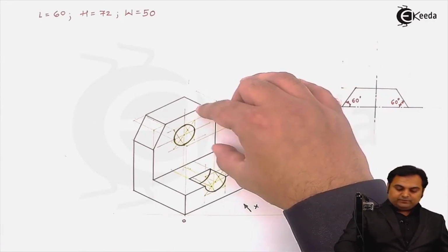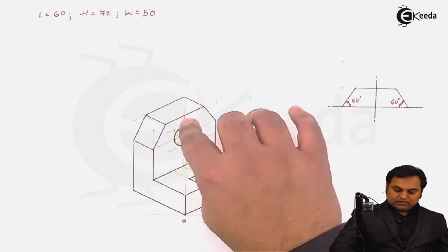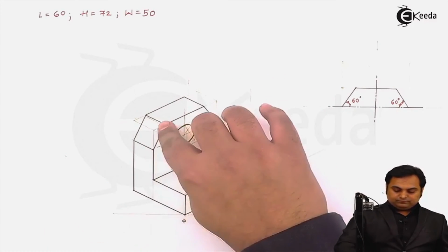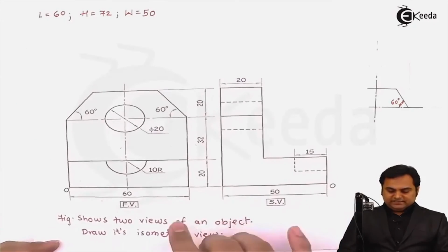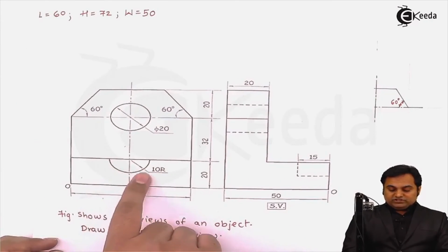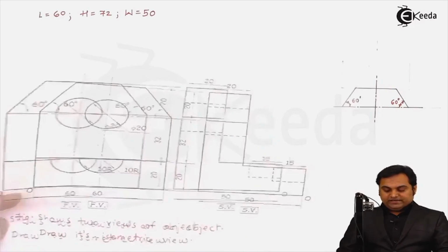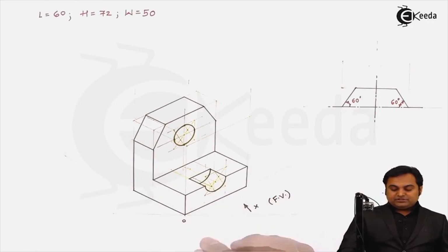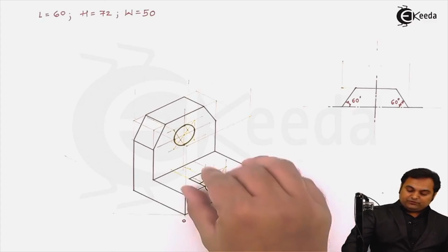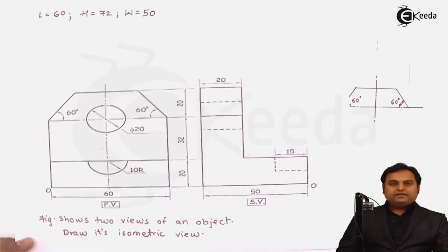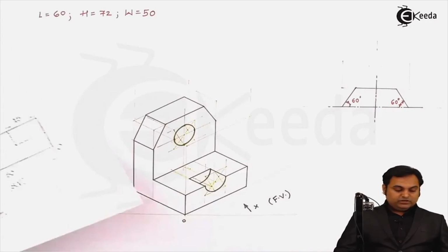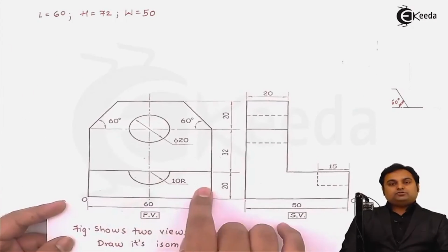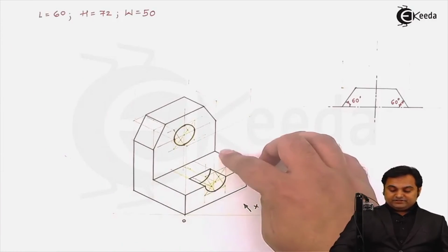That is, the vertical plate is seen along with the circular hole and inclined lines. Horizontal plate is seen, which is having semicircular hole in that. So here there is a semicircular hole or groove up to 15 mm depth. Next, between the vertical and horizontal blocks, there will be a dark line like in this orthographic drawing that indicates change of plane.